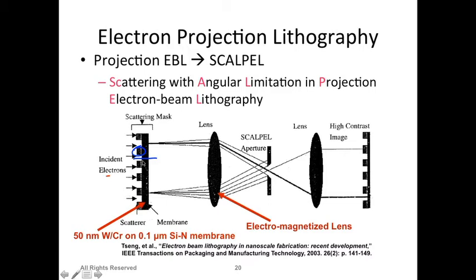So the basic idea is, when the electrons come and shine on the surface, wherever we have a thin silicon nitride membrane, like in this area for example, the electron would scatter. When electrons come and hit the surface, they pass through the material, and they will scatter because they interact with the material electrons and all that. Because of that scattering, you will see some scattering of the electron beam here, and then you use apertures or electromagnetic lenses to focus them in certain areas.